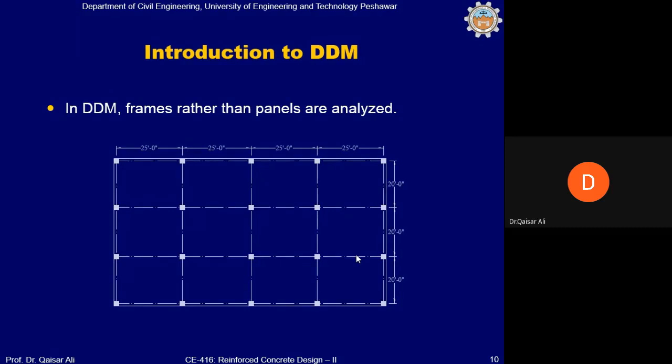So for 20 stories, 11.5 or 11 multiplied by 20, around 220 feet of height will be required. And if there is a restriction on the overall height of the building, which, as I said earlier, is 200 feet, then only 16 or 17 stories will be possible to construct in that locality.